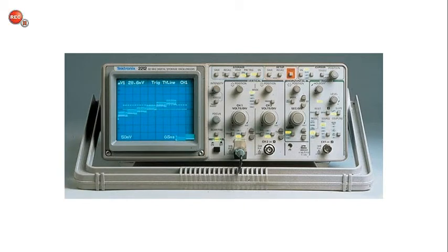So digital multimeters and analog meters are very good at measuring DC voltages because the DC voltage is constant. Those types of meters are bench meters. They can measure AC voltages as well, but they give us the RMS value, which again is the effective value for the same power dissipation properties as a DC circuit. And so that doesn't give us the full picture of the waveform.